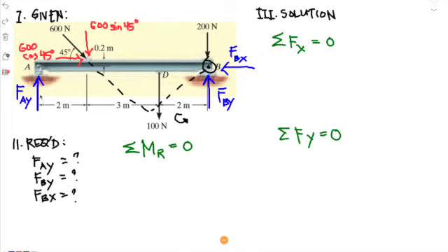So it's safe to assume that it is going up, so its effect on point B should be a clockwise moment. So right now we can also say that the assumption for FAY is already correct. Again, it's okay if your assumption is in the other direction. Later on you will just get a negative value and you just need to reverse your assumption in order to get the correct sense of your force. What about FBY?